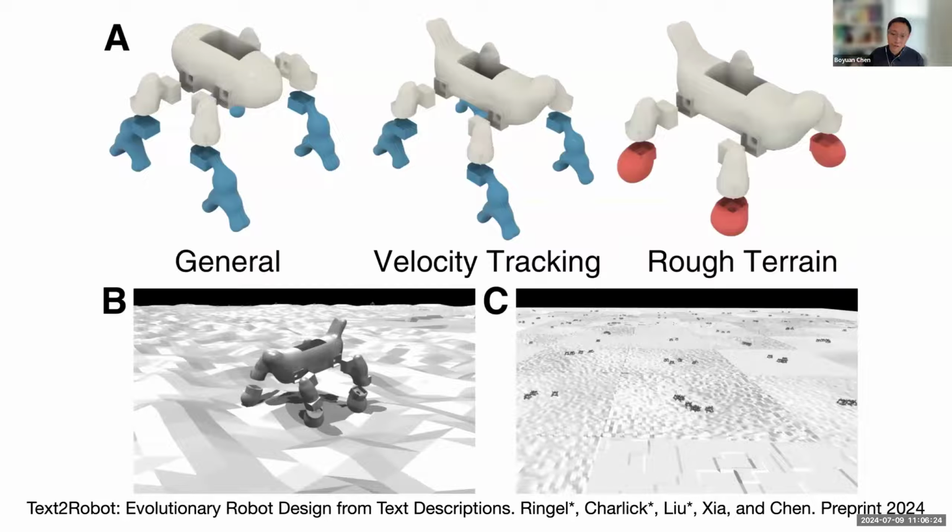But when you train the robots on rough terrain, the foot turns out to need some sort of round shape. And when we observe the walking policy of these robots, you will see that the robots that look more like this sort of two-finger feet typically get stuck on the complex terrains. On these rough terrains, a round foot fits better. So you can see all kinds of interesting improvements, even just by changing the environment, in how robot design can respond to it.